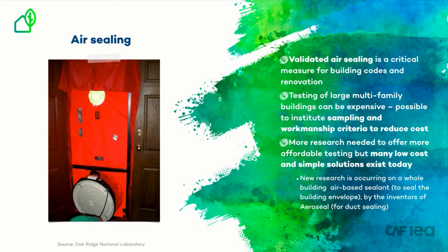This provides a pressure reading that is the baseline for measuring how much air leaks out over a given amount of time. This can be measured in either volumes of air per hour per meter squared of the building envelope, or in air changes per hour, that is, how many times the volume of the air in the building is renovated in 1 hour. This is a costly and complicated measurement to take. More research is needed to find simpler ways of assessing the tightness of a building envelope.